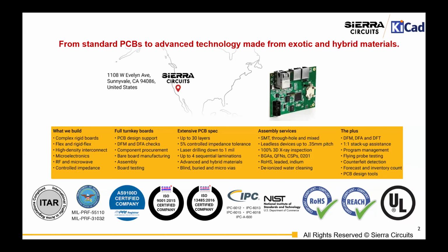Seth, while people are doing that, you said something which I wanted to ask you about. The non-plated through hole inside the SMT, in the SMD pad. For us as a manufacturer, that is a via-in-pad that we have to plate over in order to assemble properly. What can the user do for that? Can they add those to a drill chart relatively easily? Is there any automation they can do there?